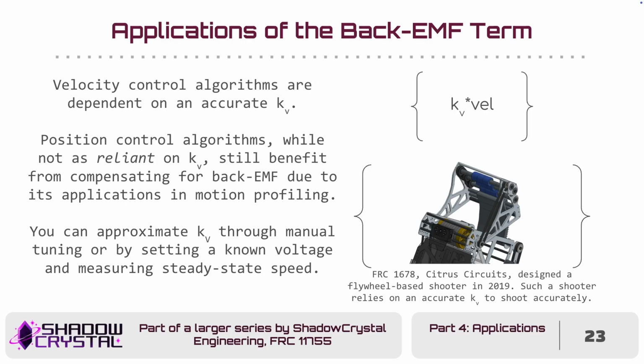Back EMF. This is your back EMF term. And the significance of back EMF is pretty large in most mechanisms. Velocity control algorithms, as I previously touched on, are completely dependent on a stable Kv in order to hold a certain velocity. I took this image of Citrus Circuits' 2019 shooter from FRCdesign.org.